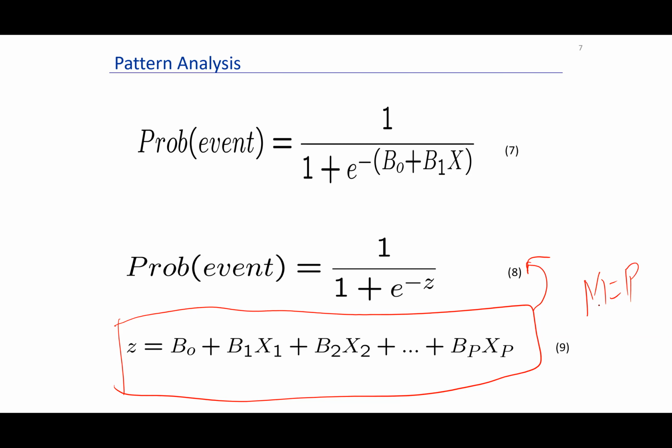But if you take a subset of m, you could call them p features, just like how in poles we talked about extracting dominant poles, especially since we know the poles closer to the unit circle are significant. So similar to that, when you extract a subset of the features, which is called the feature selection process, then we have p of these features. So here the features are nothing but x1, x2, all the way to xp. So your x could be either AR coefficients, or poles, or cepstral coefficients. So you have three different feature models that you can feed into that.